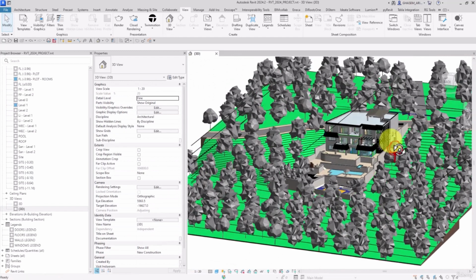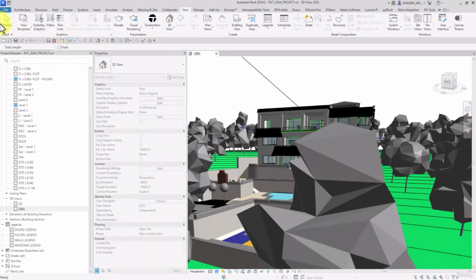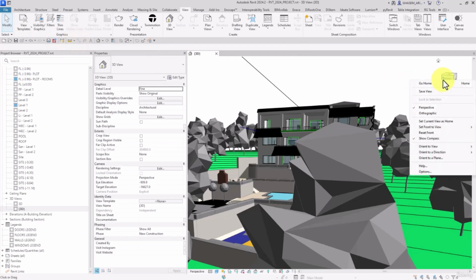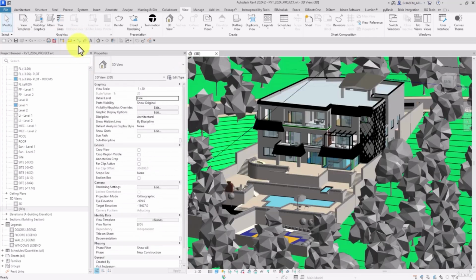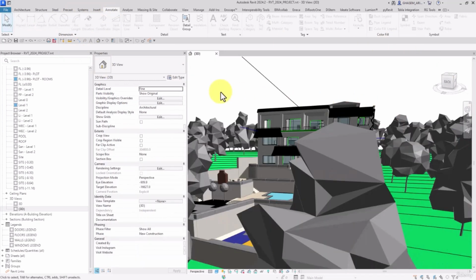And the point here about the Revit software is that the measure tool works in the orthographic and perspective views in this version, but we can only use the dimension lines in orthographic, not perspective. Okay, so we can use measure in both, but we can use dimension lines only on orthographic.